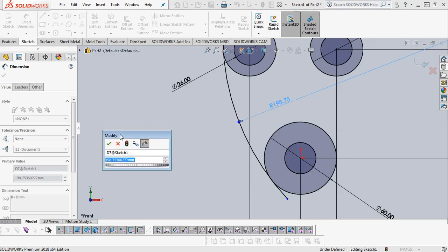Because we can measure the arc radius, not the diameter, practically. While checking, we will use a radius gauge. So that's why we will give the radius. Usually we will specify the radius. So the radius is 105 millimeters.